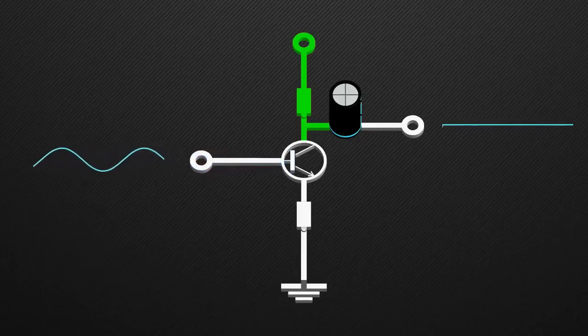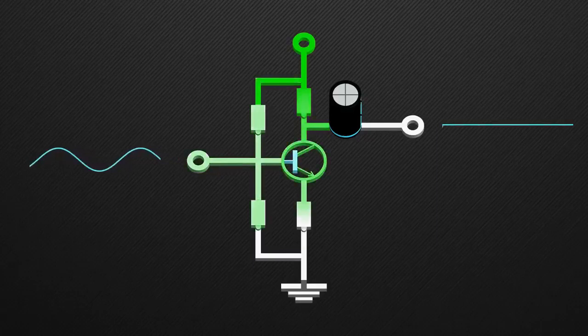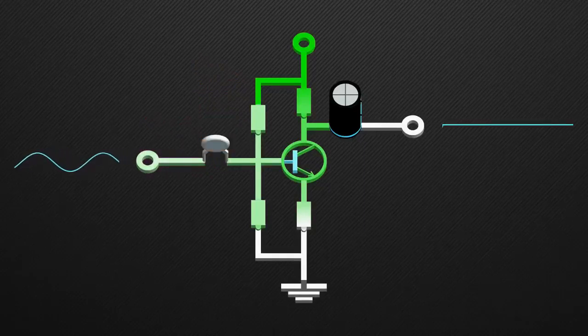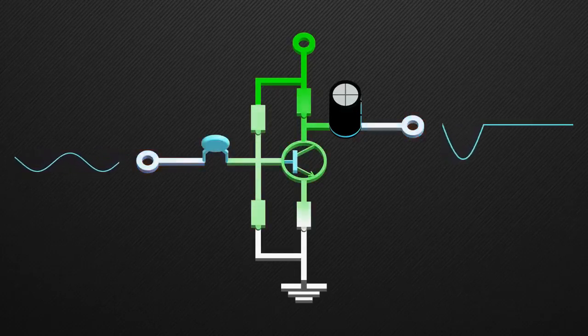And to do that, we add a voltage divider here. This will provide the required bias to the voltage of the signal. Now, a complete waveform of the signal can be obtained at the output. But, now the transistor is always on. Also, this DC bias voltage can interfere with the source of the input signal. Hence, we add a capacitor here. The capacitor will block DC from any of the directions and allow only the AC signal to pass.